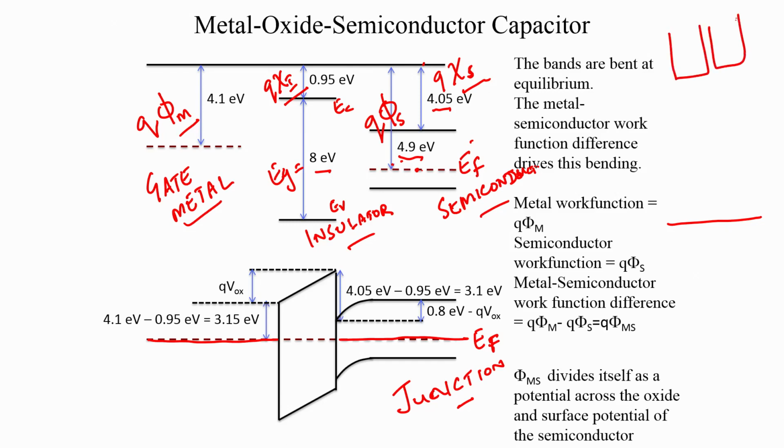So, you have these two buckets and you have less water here and more water here, and this corresponds to a Fermi level that was higher or work function that was lower, whereas this corresponds to a work function that is higher, and when you merge these two buckets, the water flows from there to here, thereby aligning the Fermi levels. Okay, so we looked at all these analogies and we had a mathematical derivation of why the Fermi levels should align at thermal equilibrium, because the flux of the carriers have to be balanced.